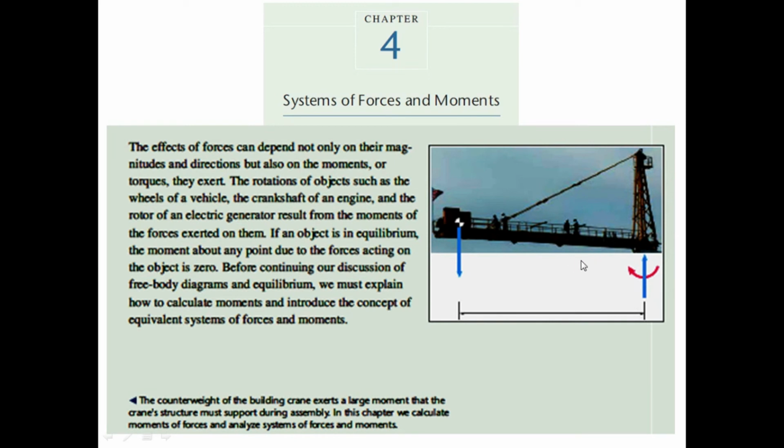You apply summation of moments: positive 200 pound feet and minus 200 pound feet. You add them and what is the result? You will be surprised, it will be 0. And for the vertical forces, 500 pounds minus 500 pounds, the result is again 0.